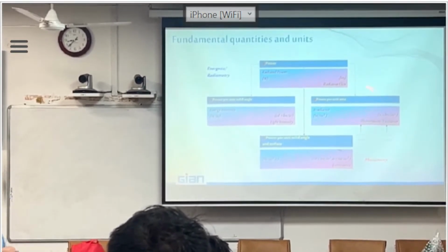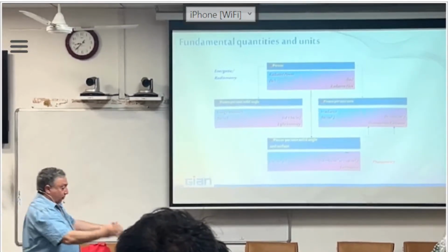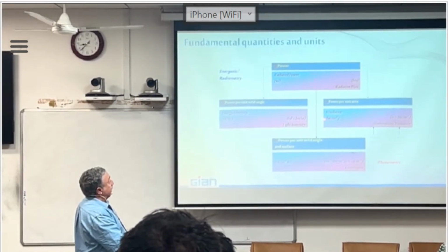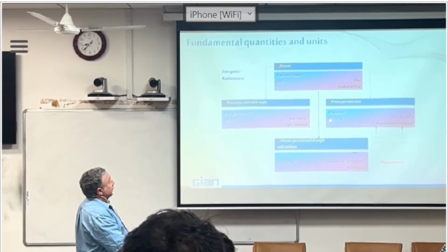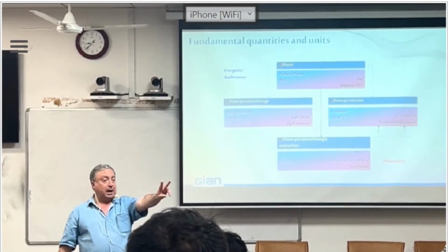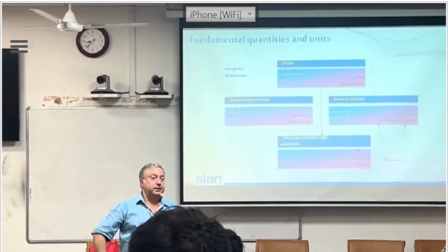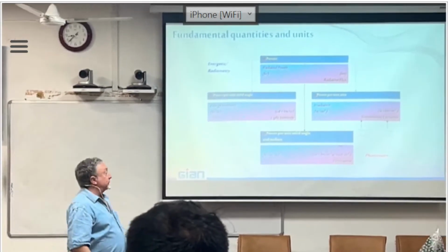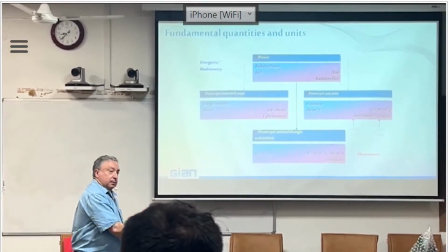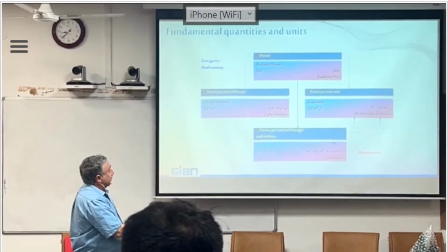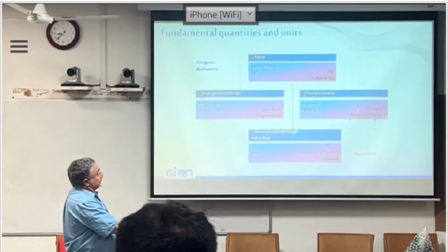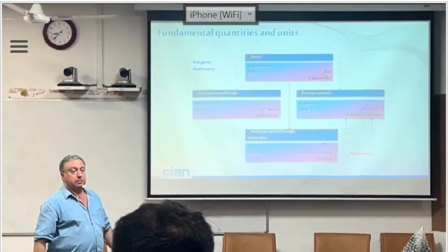If I type now the power per unit of area, the power arriving on the table here, in an energetic sense, I'm speaking about irradiance, watt per square meter. But in photometry, I have two kinds of quantities in that definition. One is the illuminance, how much light arrives at the used surface, and this is measured in lumen per square meter and has a specific name, lux.